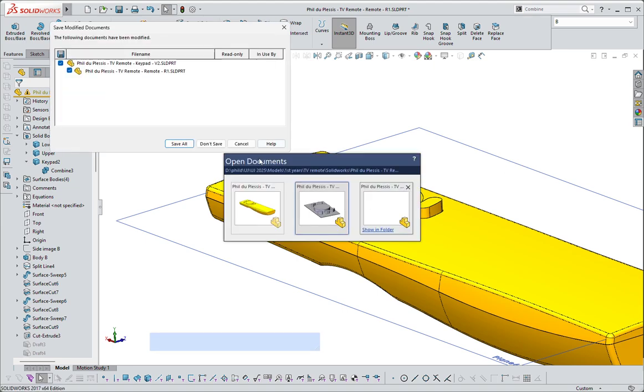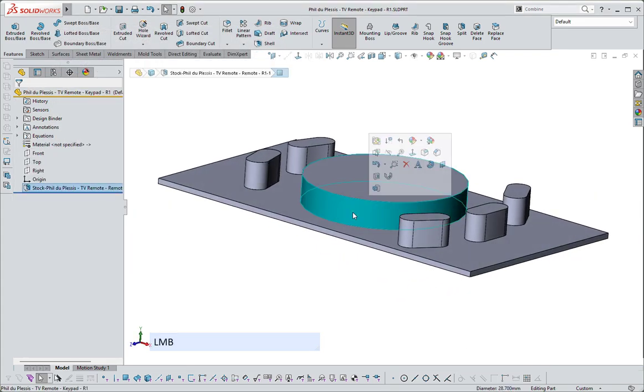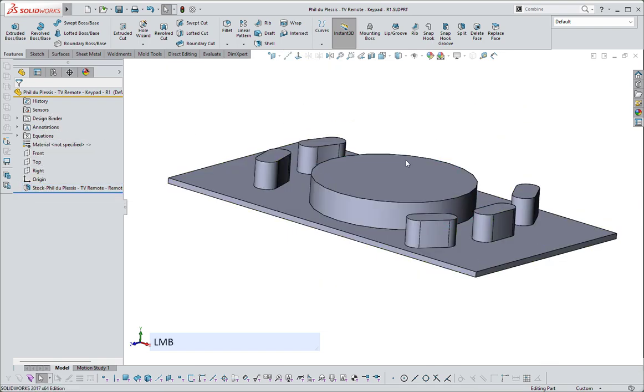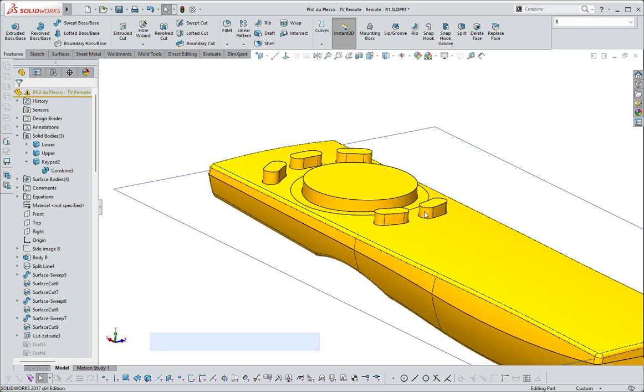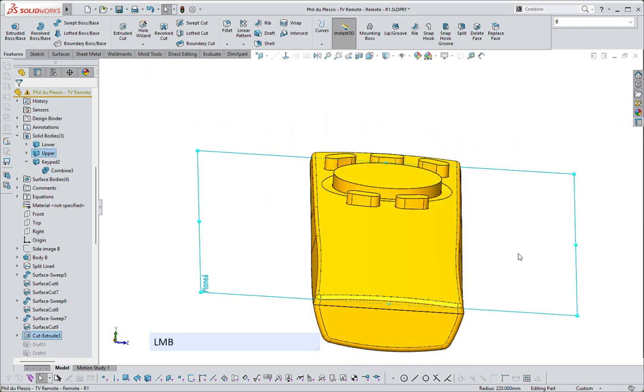Let's just close that one down. Go and save. Have a look at the height of these. These are 5 mils. You can see that there are no details in the design tree. So this file is entirely dependent at this point on what I do inside my multi-body part. So I want to slice these off so that they're just like 1/4 millimeter above that surface there.